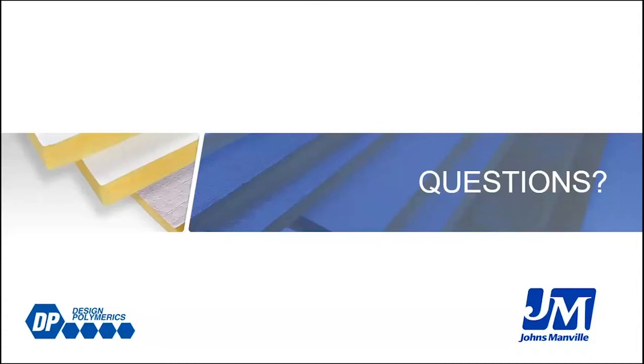Okay. The next question is also for you, Scott, and that is, some contractors have proposed in Design Assist projects to use tape in lieu of mastics. Is tape sufficient for a seal in all instances? Well, I'll clarify tape. Foil mastic tape, like I briefly discussed with our DP 240 and 340, yes. Now that tends to be much more expensive than your typical duct tape or your foil tape.